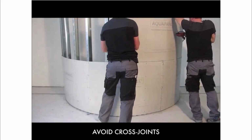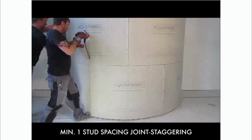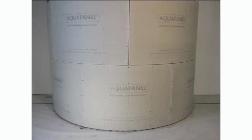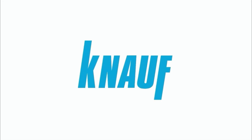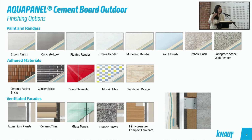Each board is laid horizontally and there are no cross joints. You have to have it in a staggered manner, just like a typical gypsum board drywall installation. Our boards, like any typical fiber cement sheet board, can receive any kind of finishes, be it painting or rendering, and can also support the weight of any cladding materials that you require on top of it.